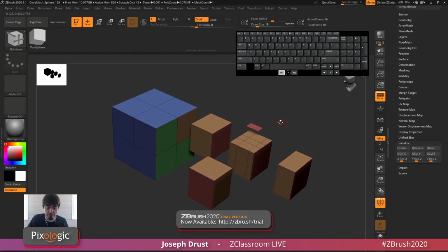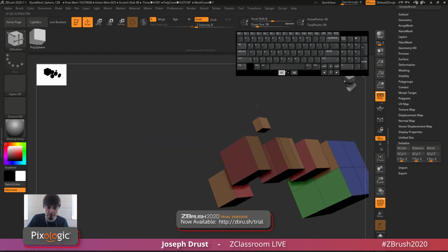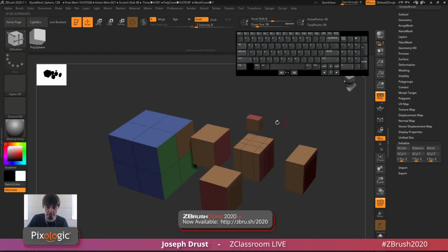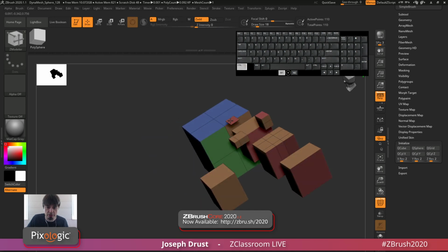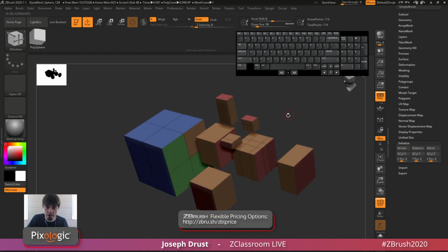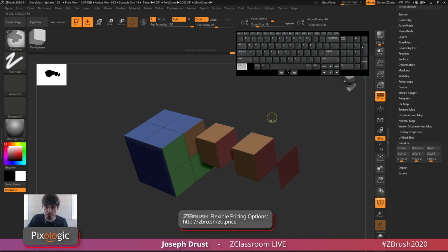another little sliver there. Now, since this is a single-sided piece of geometry here, if I Q-mesh it again, it's going to seal it up and make it all nice and clean there. So you can use that process too to come through and pull things out and keep adding different topology there as you work. Now, another option that was just holding down the Control key while you're performing the Q-mesh action